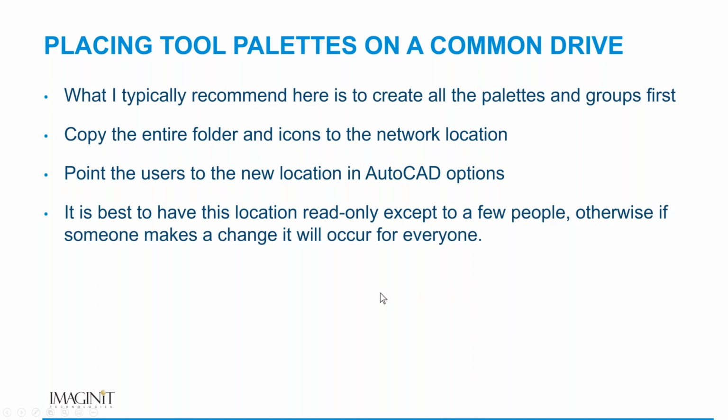If you use Dropbox to share your tool palette path and blocks, it makes it faster since files are stored on each computer. OneDrive can't handle sharing tool palette paths. No, OneDrive cannot. Dropbox can do it because Dropbox is essentially creating a local copy of that information, Brett, so that does work as well.